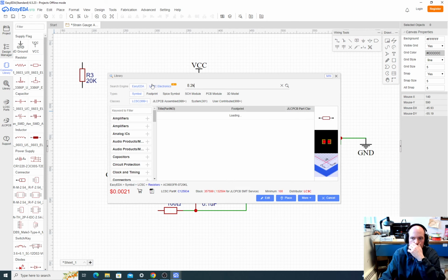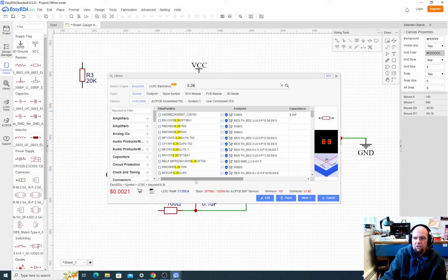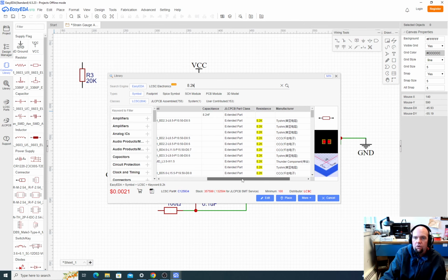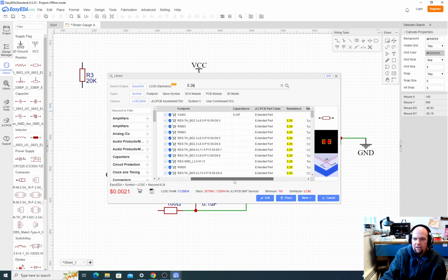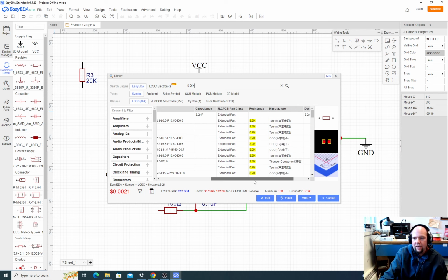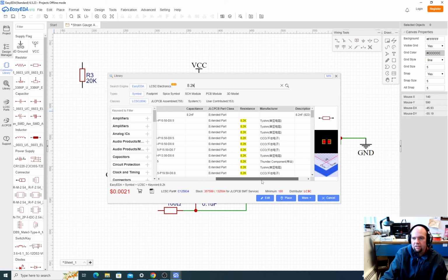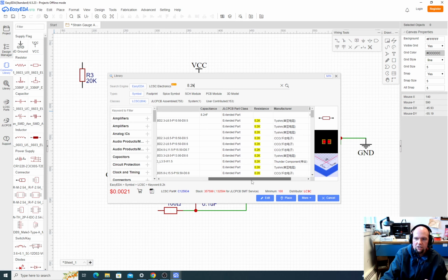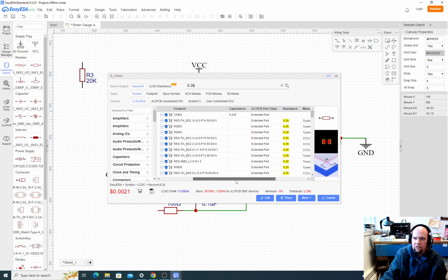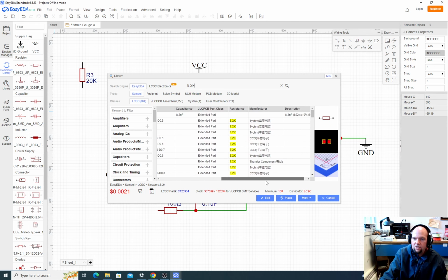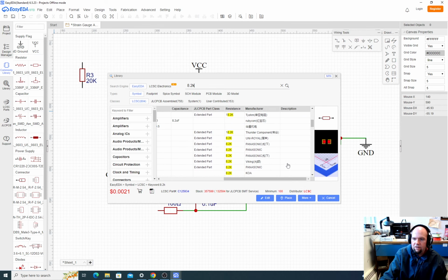Now resistors have standard values, so you can't get any old resistor value. An 8.2K is one of the standard ones, but a lot of students will do a calculation and say, oh, I need an 8.257 ohm resistor. You can't necessarily buy that, or if you can, it's possibly very expensive. So a lot of times with resistors, you're limited to the standard ones. 8.2K, 0603. Yeah, these are all fine.